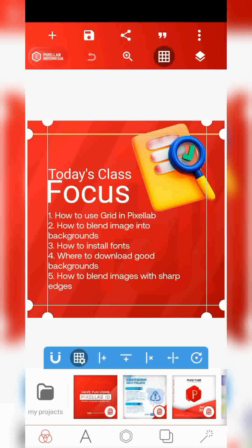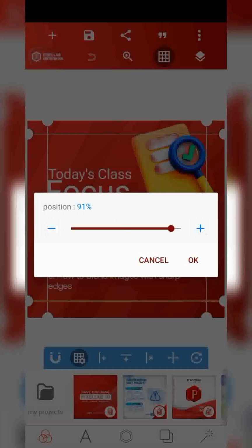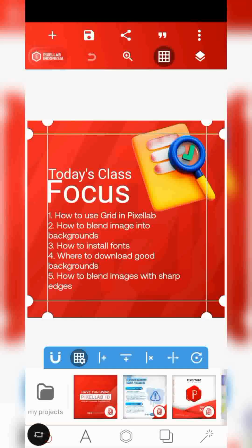So just in case you might not be accurate enough to move these lines to the particular point they are supposed to be, you can adjust it automatically. After clicking on that particular line you want to adjust, click on the icon at the right, the icon that has two arrows facing both sides, that's close to the last icon at the right.